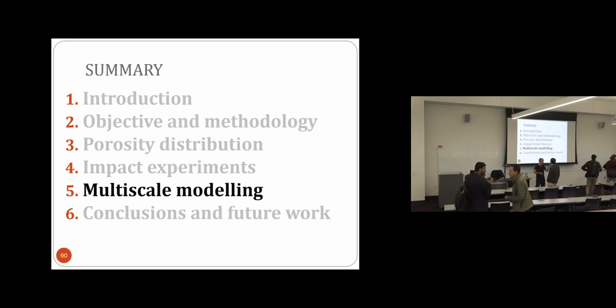So this is why many of these things are not published. Basically what we are doing again is comparing the tomography before and the tomography after, but there is a limitation for the new voids, which is the resolution of the tomograph. If they are very small, then forget it. But some of them have grown a lot, so we can track them. The resolution we have is something like 1.5 micrometers. Less than this, we don't see.